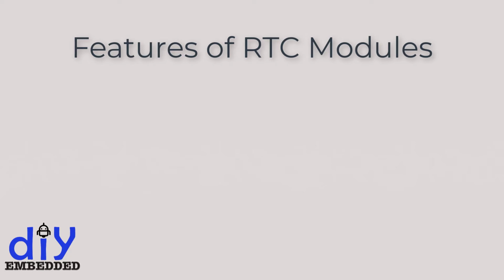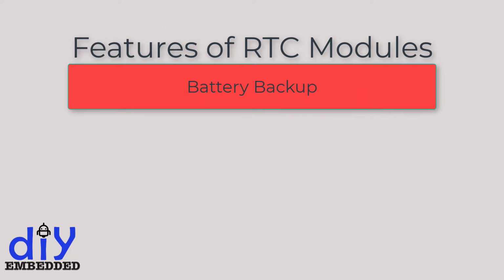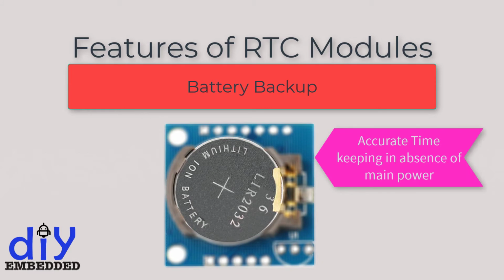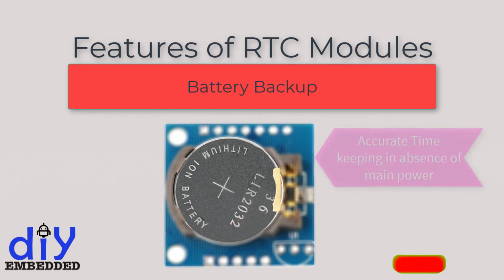Another important feature is battery backup. The DS1307 incorporates a battery input and maintains accurate timekeeping when main power to the module is not available. The built-in power sense circuit continuously monitors the status of VCC to detect power failures and automatically switches to the backup supply. So, you need not worry about power outages, your microcontroller can still keep track of time.